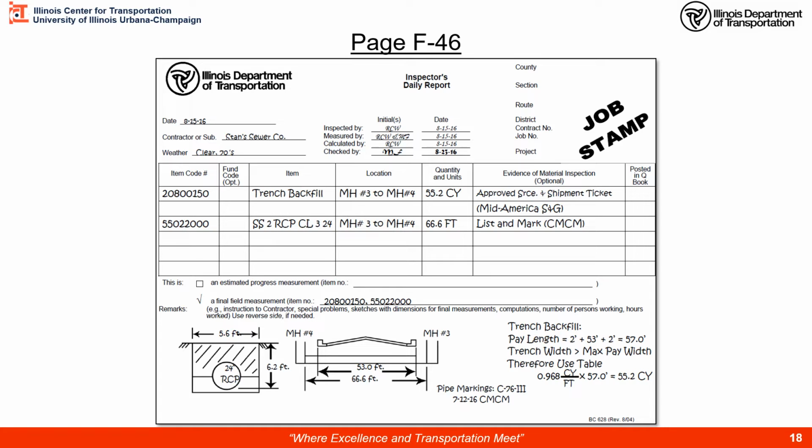So that's 2 plus 1 is 3. We got 3 and 3. That ends up being 5.5 feet in width that we will pay for. The contractor dug wider than that, just barely meets it, so we can pay for this whole width of the trench.